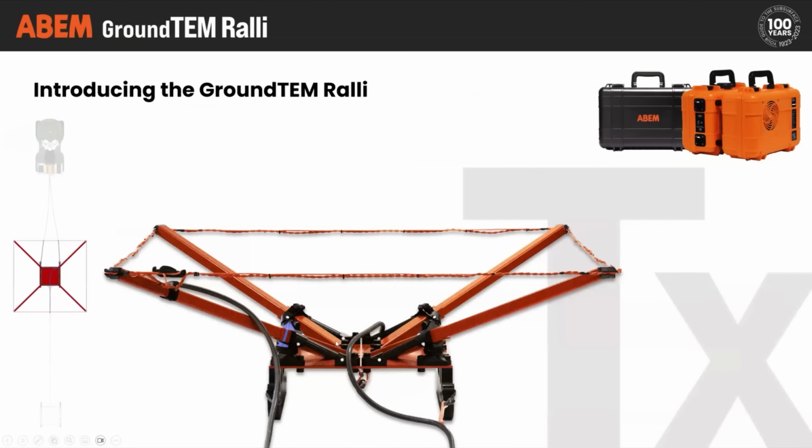Transmitter, this is mounted on sleds, no wheels. It's a sled mounted affair with these wings that are made of fiberglass, and that carries the transmitter loop or transmitter coil, depending on which configuration we've chosen. Because this is a 30 amp transmitter, we have to run this on a much larger power source. The recommended power source is a 100 amp hour lithium ion battery, and the system comes with a suitcase for mounting that battery in, and then all you have to deal with is plugging the charging unit into one side or taking the power out from it and plugging that into the instrument itself.